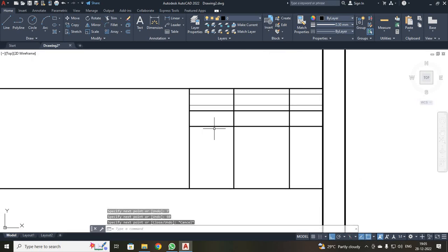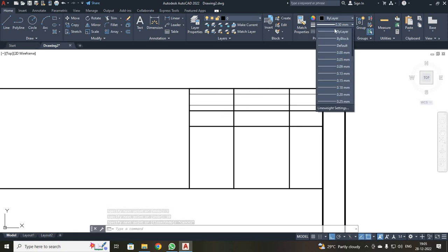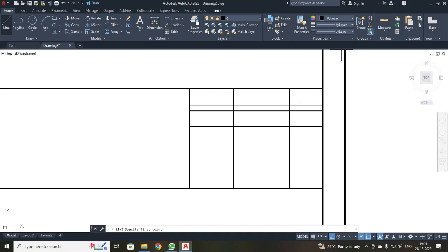Now I am going to zoom it. I am going to draw these thin lines. For that, once again I am going to just click your line. Over here I started it. First click over here, 2 mm, enter. First click your line, move to your y direction 2 mm, enter, 60, enter. On your y direction it is 3 mm, enter, and 60 mm, enter.